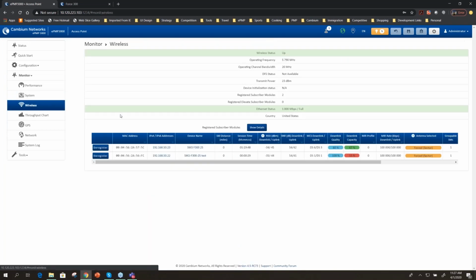When you go to the wireless, obviously you're going to see your modulation rates, your SNR, something that we talk about quite a bit, that even with a good RSSI, good SNR, you may have interference that's causing problems in the link, or your capacity is down or quality is down. Capacity, just so you're aware, is more or less the link capacity in relation to the maximum MCS.